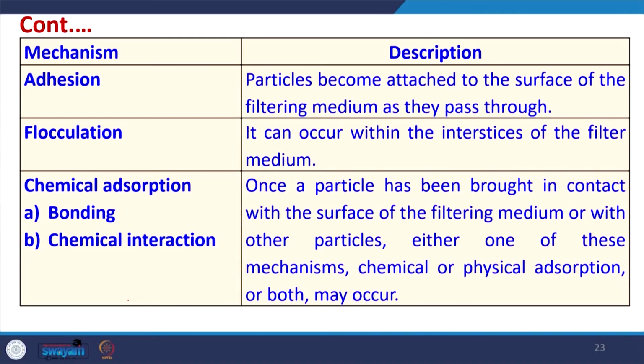Once a particle has been brought in contact with the surface of the filter medium, adsorption may occur, and that adsorption may be chemical or physical or both. It is possible that only van der Waals force of attraction is playing some role, or a chemical bonding may also occur. So, it may depend upon that.